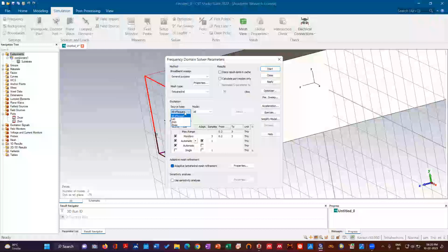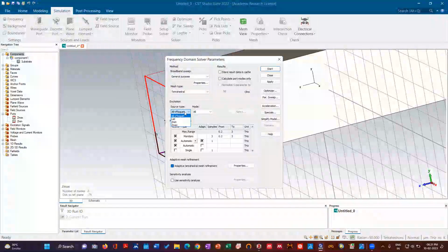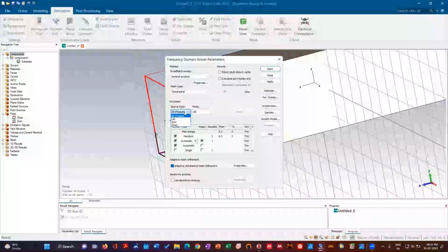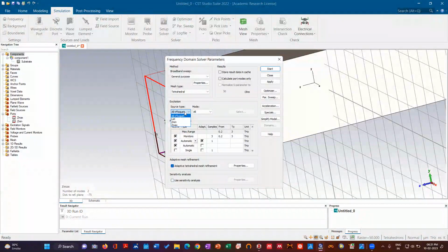Some basic questions. See, by default it is taking either Zmax or Zmin, right? But if you want to excite both the ports, you can see all the results, for example S21, S22, S11, like that. One means max, and two means min. You just map that information, and you will get all the related information, cross polarization, co-polarization, everything. That's why I think he told that, right?